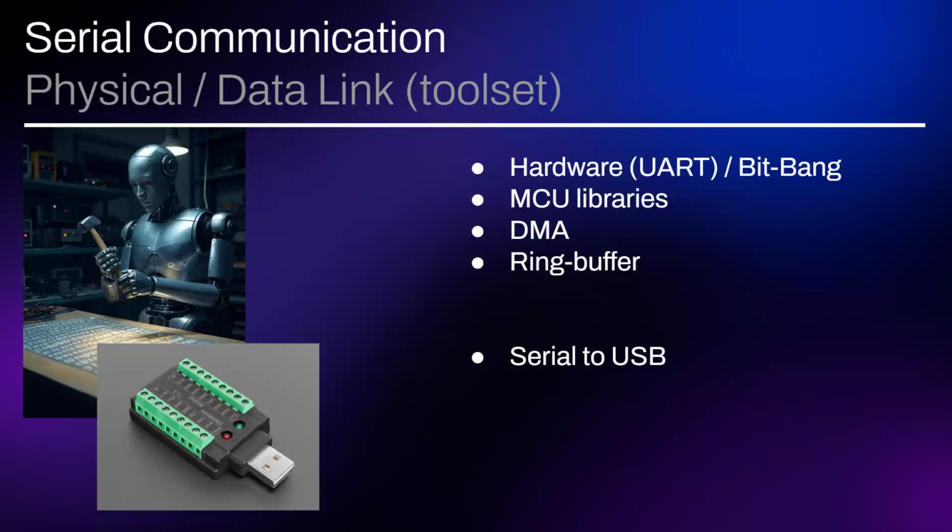But we do have USB. What does USB stand for? Universal Serial Bus. So it's a serial, but it's a bus. It's not quite what we're talking about, but there are these translator devices. Sometimes they look like this. Sometimes they look like just an ordinary cable you can't even see, but there's always a little chip in there that's translating the serial information into something that USB can understand. Then on your computer, you can pull that serial data, sometimes as a TTY on Linux or a serial port on Windows.